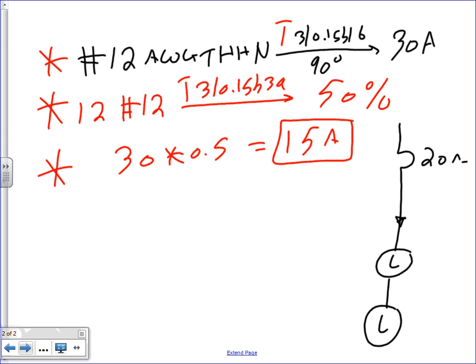So you're limited to 16 amps anyway. On a 20 amp circuit, continuously, you're limited to 16 amps. You can't pull more than 80% of a circuit breaker continuously, like lights. So after I grouped them all together, Darren, how many amps did I lose? 1 amp.